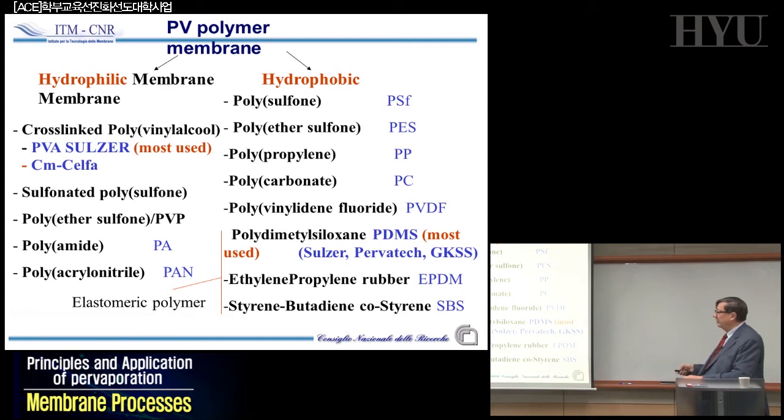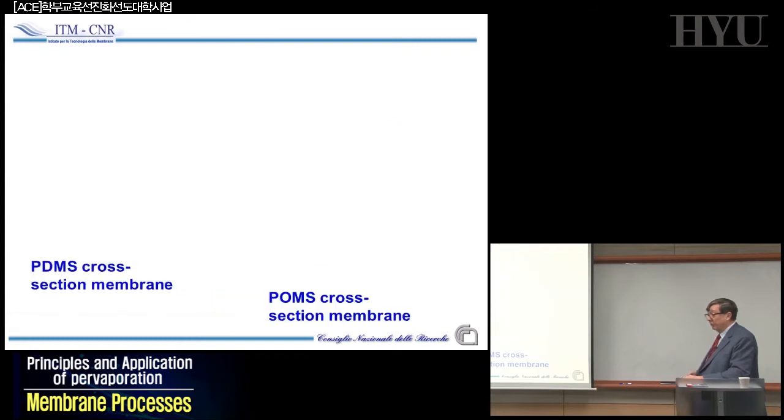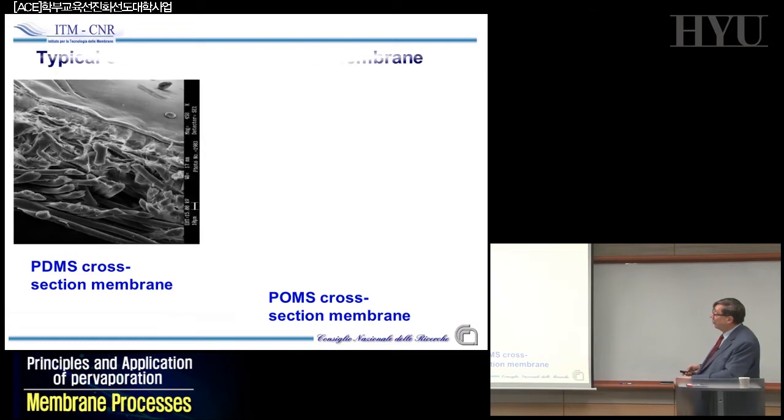And there are some new materials, styrene-butadiene copolymer, styrene, ethylene, propylene rubber, etc., that people are developing. There are new applications in which people are trying, and that's the one that I was mentioning, no more just alcohol, that is the most traditional, but we will see a few examples of application at industrial level, in processes in which new material has to be identified, having good selectivity in terms of permeation and solubilization. And all these membranes, as I was mentioning, are normally asymmetric.